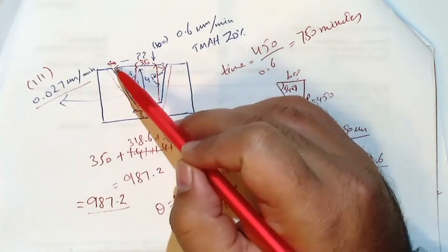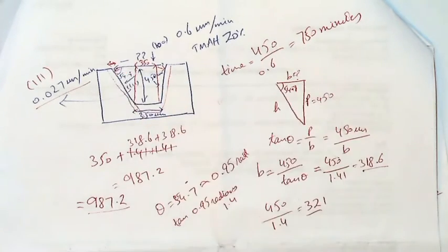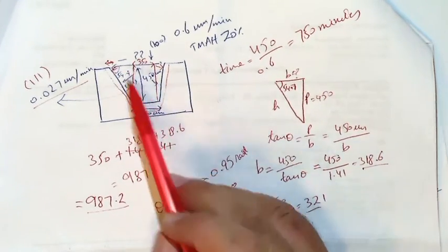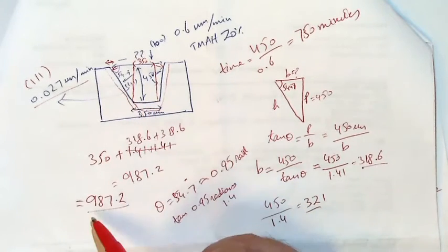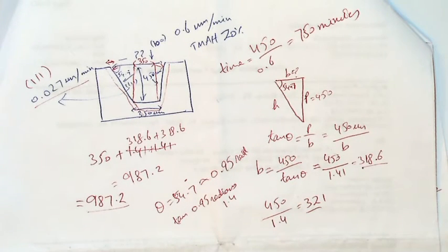Because you'll be etching on the sides also, when you look at your window, this window will be 987 plus something more. It's not going only downwards. And that rate I gave you, 0.027 per minute, that's how it's etching on the side.